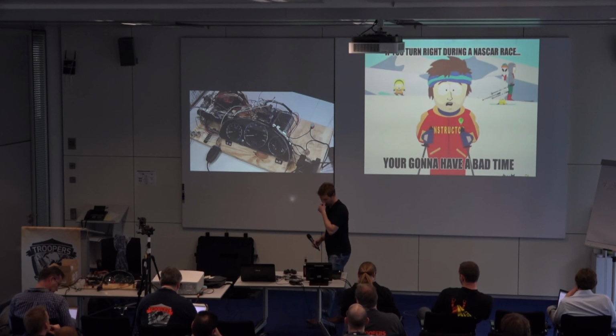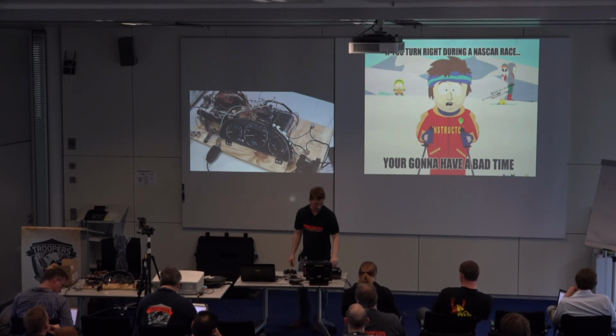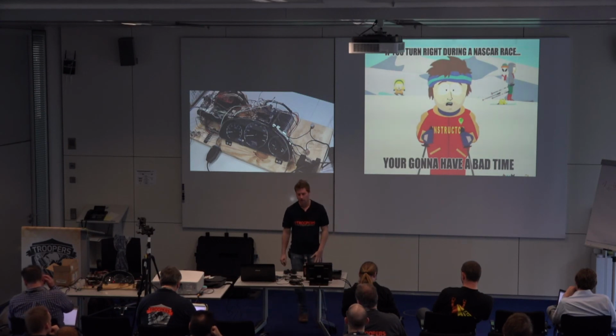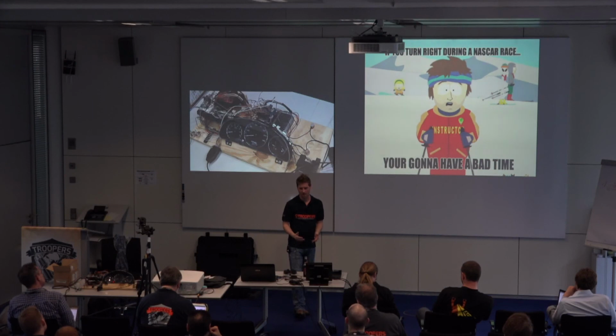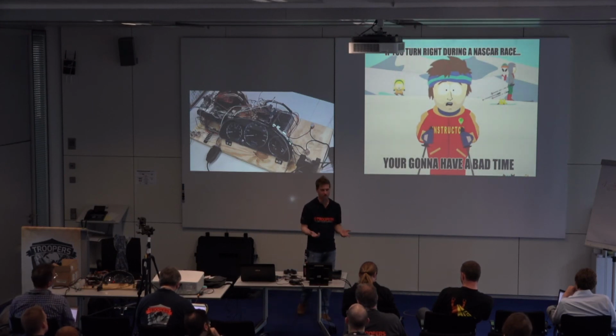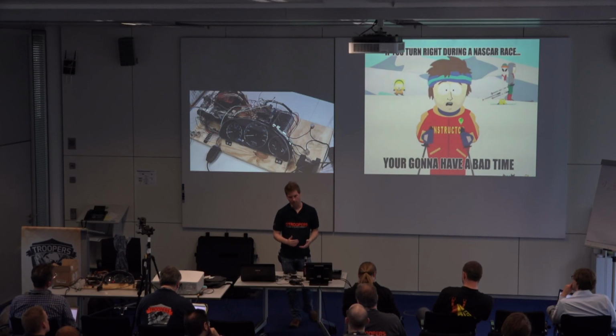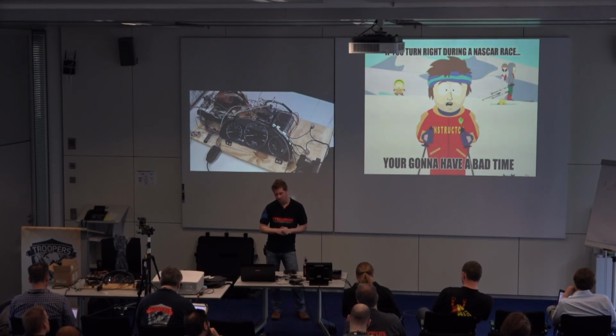That's one of the big reasons the Cavalry exists right now, to bring out from a security perspective some of the shortcomings for things, and there's varying reasons for different stuff. From a security perspective, we see things like CAN, and we go, oh my God, that's the worst design ever. But it really isn't for what the point of it is. It's really to get messages there very quickly. It's very fault tolerant on environmental issues. That's why you have the two wires that separate their voltage.